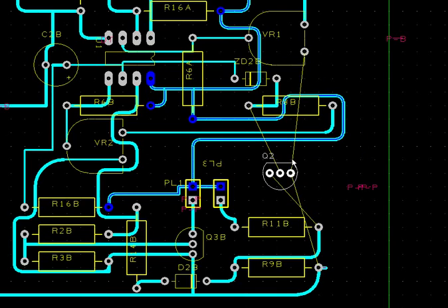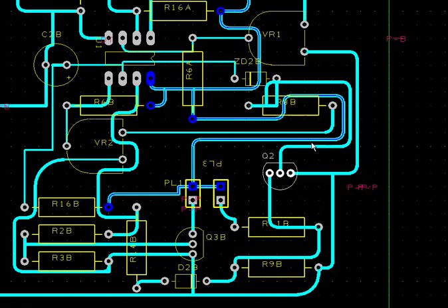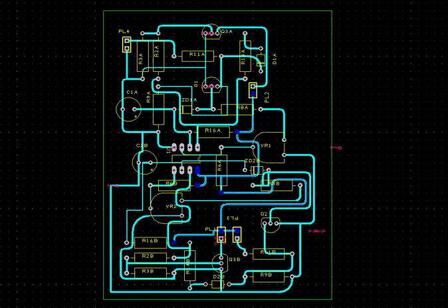So we need to get the one on the inside first. That's on the inside, it should go all the way around. So let's try getting that first. Right, that's gone. And that one's gone around the outside. That's better. Always take the line for the inside first if there's an outer one, because if you take the outer one first, it could block the path of the inside one. Right, that's gone. We've got that rerouted, and it's getting more condensed still. Look at that, it's even smaller than it was before.